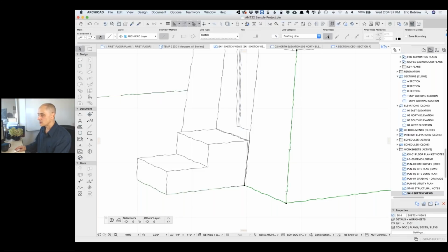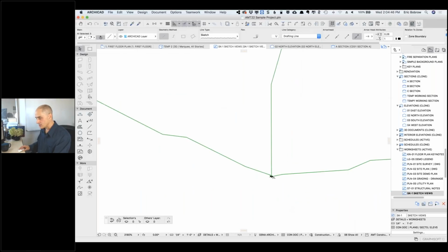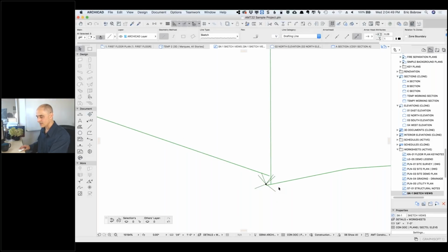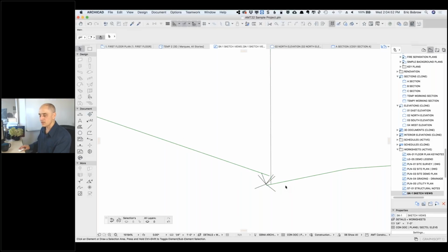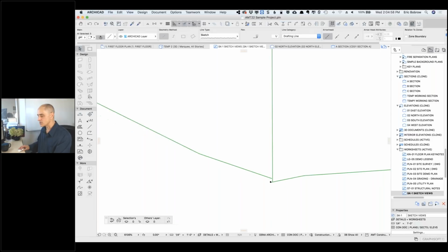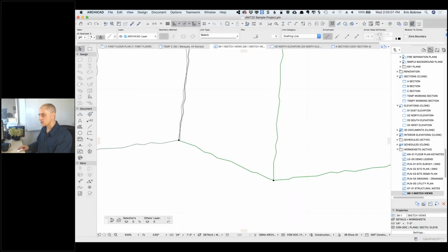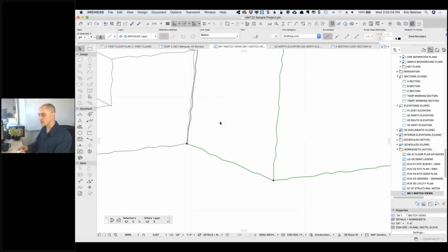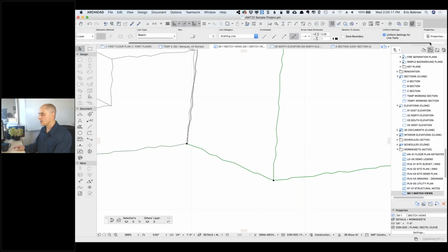Now, lines with no arrowhead. If I say, give me arrowheads at both ends, well, there are these little bitty arrowheads there. Well, that's not really what he means. He means an arrowhead that's actually simplified. So let's just undo. Now I've got these lines still selected. When I undo, it shows the ones selected that I had worked on. And let's look at the arrowhead. Let me put it in, we'll just put it on arrowhead, and then let's look at the arrowhead style here.